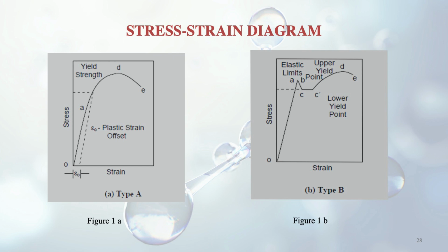But all this stress is actually only engineering stress. It is not true stress, because when necking is taking place, the original cross-sectional area is changing and the area is very less in reality. So true stress should go up, but it is not going up because we are discussing only the engineering stress. So this was about one type of material.